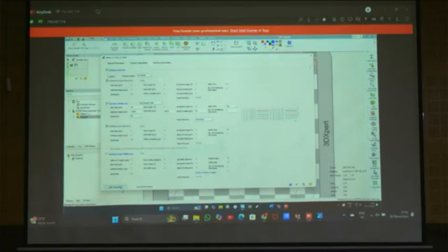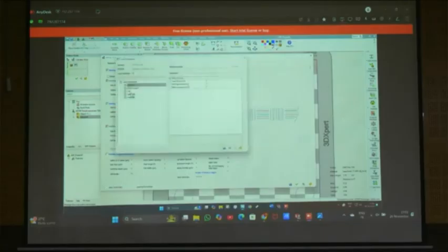Laser parameters you can change here, part right. 100 watts it is there, you can keep it as 90 watts also, and 1200 mm layer. These are the default parameters we are using here. And if you want to keep 600 or 1000 you can do that also here.